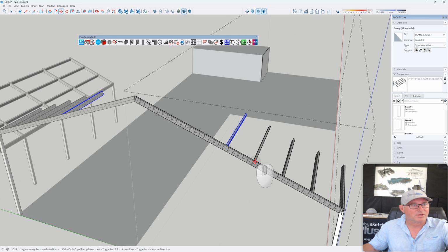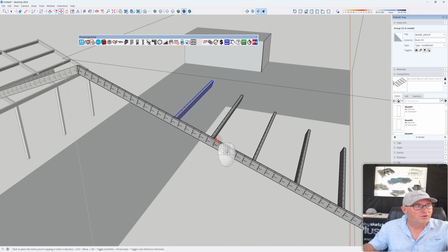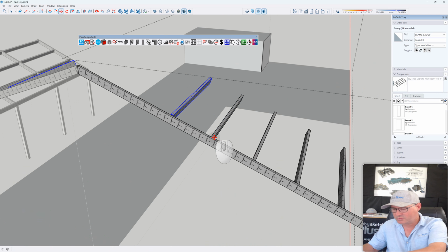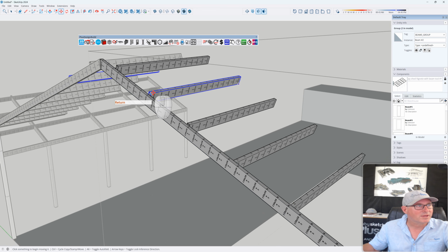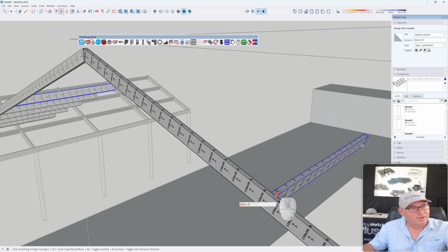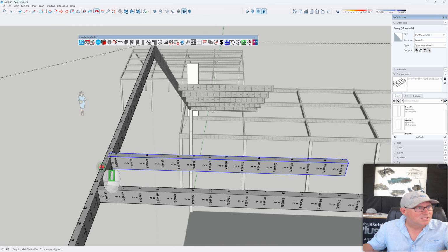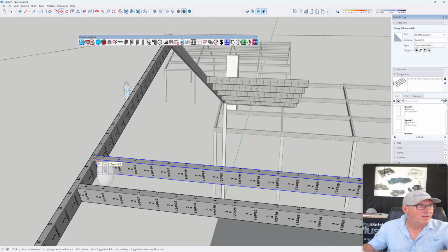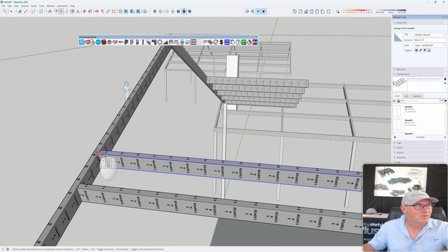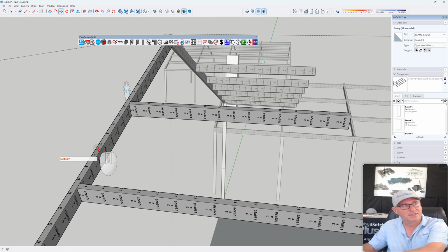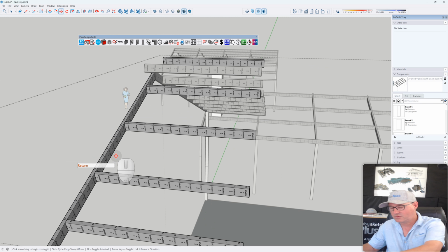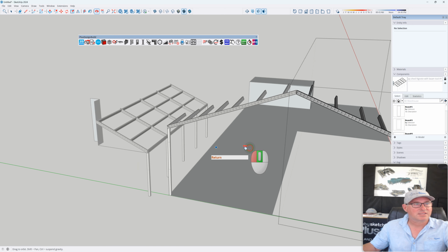I can also work out my spacings again here. Move, Control, times 3. Right, you can see I didn't move that properly, guys. I'm kind of hurrying there a little bit. So here, grab the right spot, follow it along, type in your spacing, but it is important that you actually get a crimson line. It says there on edge of beam. If I move up, you'll notice that, there we go, I got a crimson line. I can type in my spacing, 1200, enter, times 3. Oh, there's too many, times 2, right? And now you can see I'm getting my beams.